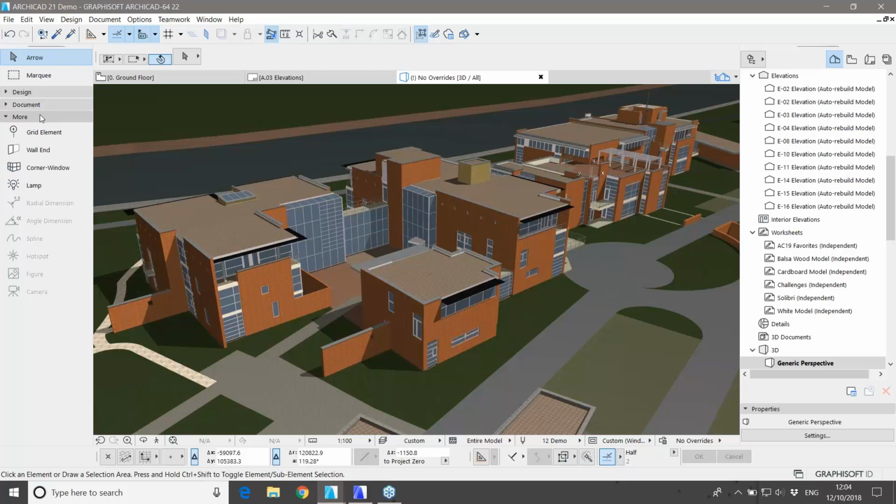Because we got the latest Cinema rendering engine, so the latest Maxon engine, we've got the lamp tool here, which will be quite useful for your internal scenes in case you want some light sources on your renders. This could be quite useful for your RCPs as well. That's why we got the camera tool. So you can again adjust your scenes to a certain angle to be rendered natively in ArchiCAD without having to import and export them into third-party software either. If you place multiple cameras in ArchiCAD, you can actually do fly-throughs, so you could just save out MP4 movies. So when you do presentations about your building, you just run it in the background.